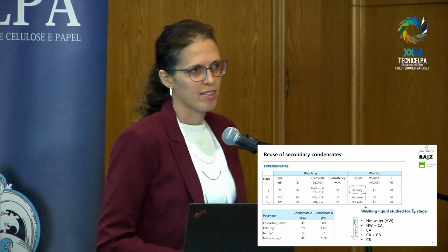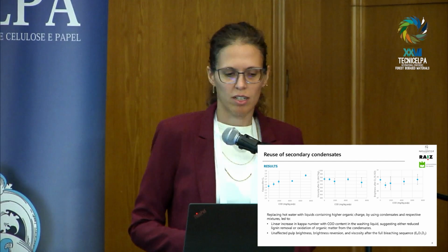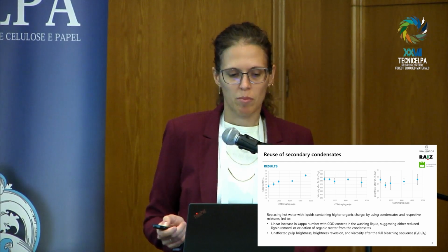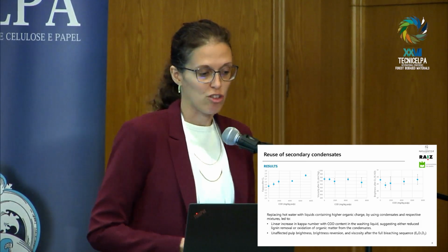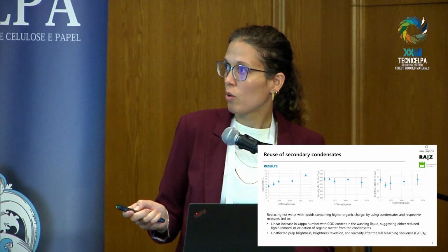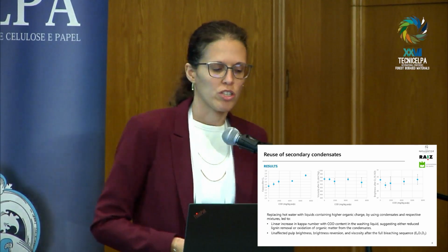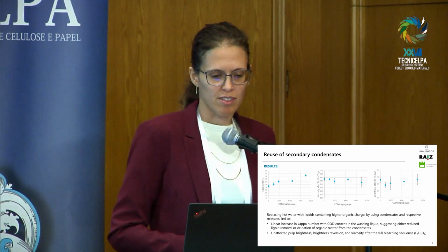Then we analyze the pulp properties, the filtrates, and the main conclusions are here, the main results. So the kappa number after the extraction stage increased almost linearly with the COD of the washing liquid.